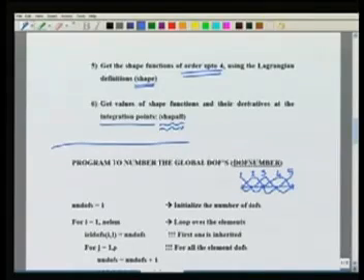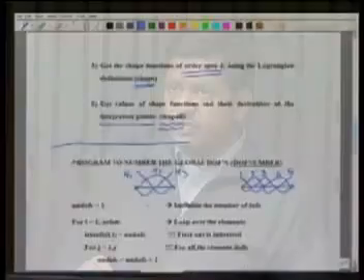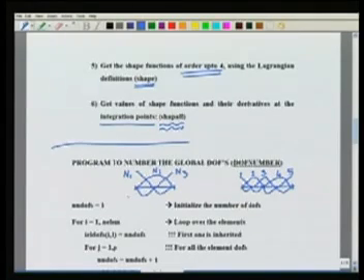So what we do is, we have the subroutine or the function called DOF number, where we will go element by element, construct these global basis functions and give a one-to-one correspondence between these global basis functions and the element level degree of freedom. That is, if I am in element 2, for example, this was my N1, this was my N2 and this was my N3 for element 2. Now which global basis functions phi does this N1, N2, N3 correspond to? This data we are going to construct in this routine. So if you see, the local N1, that is the element 2's 1, corresponds to global 3, 2 corresponds to 4 and 3 corresponds to 5.